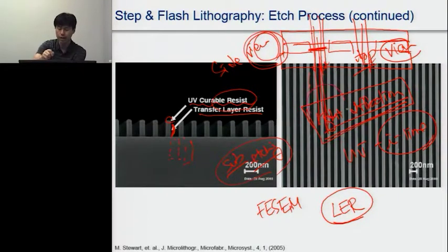and the light which has already interacted with the patterned photo mask is transferred to the resist, and then there is another issue, the reflection or sensitivities of the resist, making those patterns bigger than their designs. But for UV nano imprinting, it also has its own design on the master mold.